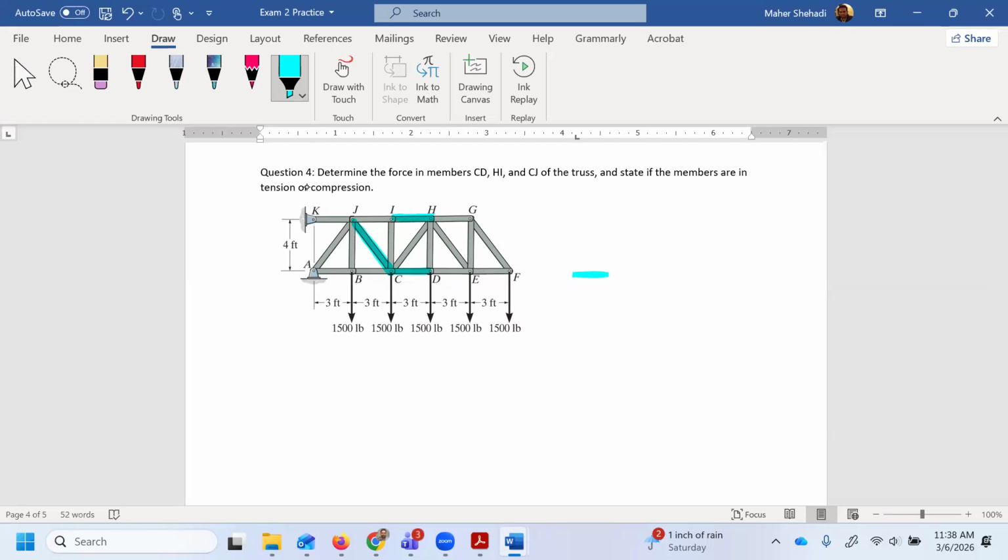I'm not going to use the method of joints here. You can see how many joints. That's actually kind of like your project, except the supports are a little different. But if you're going to use the method of joints, you have to do each and every one of these to find the forces on these members. We have here all these forces given at each one. So remember, if I'm going to use the method of sections, I can't cut through more than 3 members.